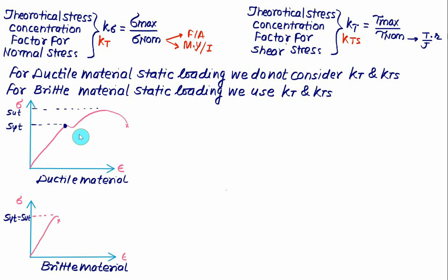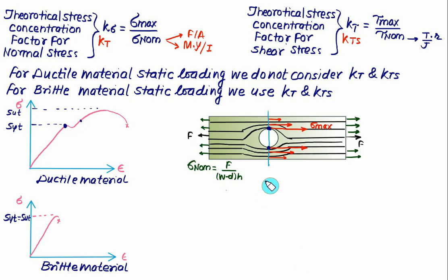So when we say the maximum stress will increase and it will come into the plastic part, then some permanent strain is produced. As we have discussed in the hole in a plate, there is a stress raiser here, that is a stress concentration. And this concentration of stress is taking place at a point. So this one is called local stress concentration. It is not over the entire part, only at the top and bottom we have a stress raiser.